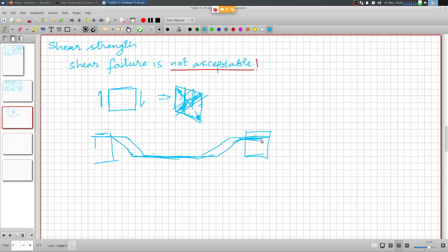So there is going to be a primary moment at the top end at the supports, and then the main moment to be resisted at the bottom fiber in the center of the span. So this kind of reinforcement detail was very popular because it seemed to address two things simultaneously: adding more primary reinforcement where it is required, and also providing adequate shear resistance directly.